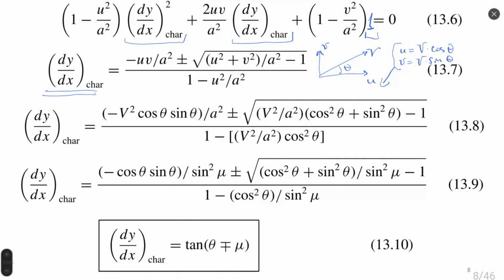Instead of Mach number, which you can see here when we analyze this equation, velocity divided by speed of sound, once we join this ratio, it will be Mach number squared, right? Same we have here, Mach number squared, and same we have here, Mach number squared. And rewriting, instead of Mach number, the Mach angle mu, which is related to Mach number, we obtain equation 9.